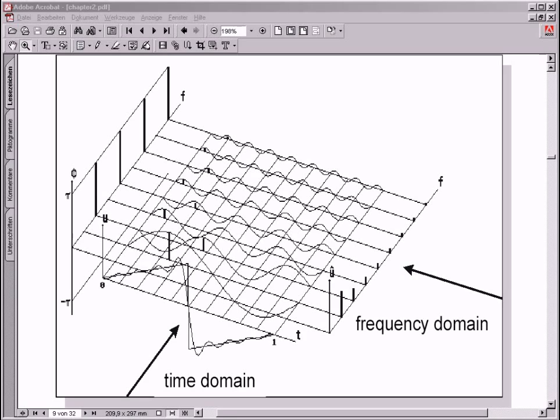For the first time, you now see the pictorial Fourier transformation. The illustration shows in a very graphic way the so-called Fourier transformation. The time and frequency domain are 2 different perspectives of the signal. A playing field for the essential sinusoidal signals, of which the periodic sawtooth signal presented here is composed, serves as the pictorial transformation between the 2 areas. The time domain results from the addition of all the sinus components, the harmonics. The frequency domain contains the data of the sinusoidal signals, amplitude and phases, plotted via the frequency f.